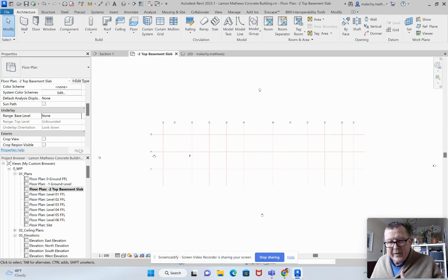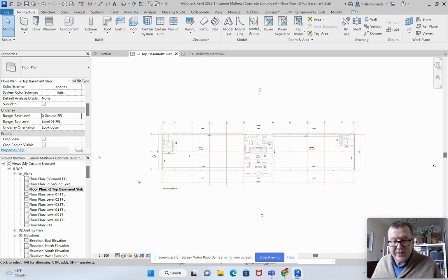Now, even though we're working below this, I still think it's very useful to have that ground finished floor level there, because it locates where the above ground walls are going to appear. So in order to get the above ground walls correct, we need to get the below ground walls set there.